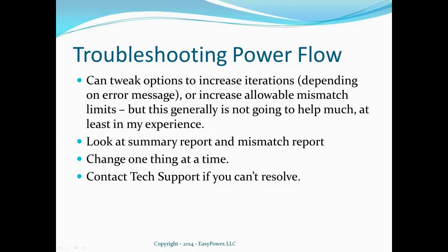Why do you have 2 scaling factors at MCC and panel? Not sure I know what you're referring to. When we do the group scaling, it's broken down by the type of equipment, whether it's a motor, generic load, MCC, or panel. So within that selection area, you can scale all the MCCs, all the panels, all the motors, but they're broken down by groups. So in that example we did.